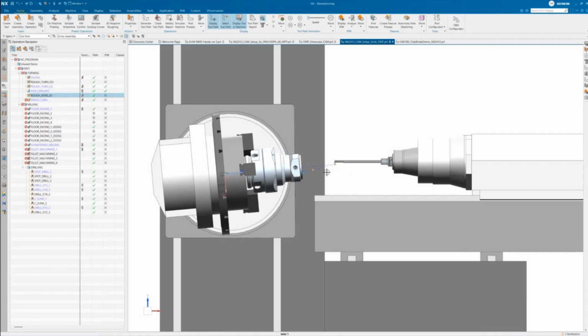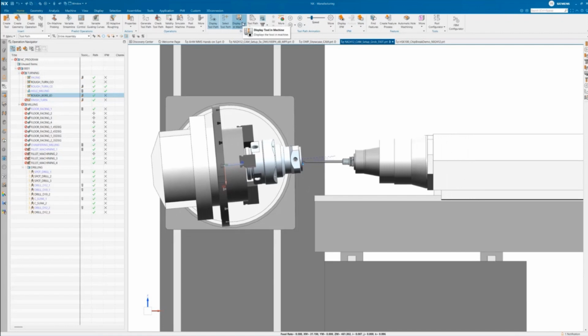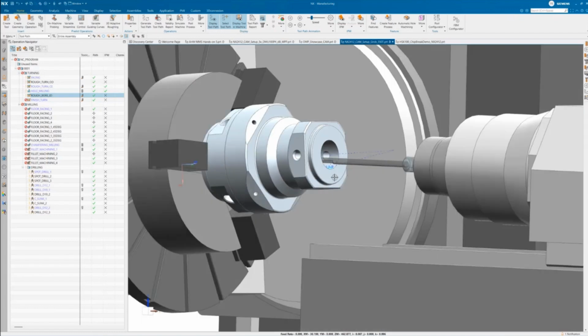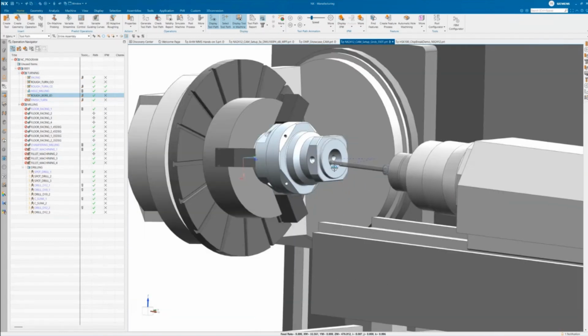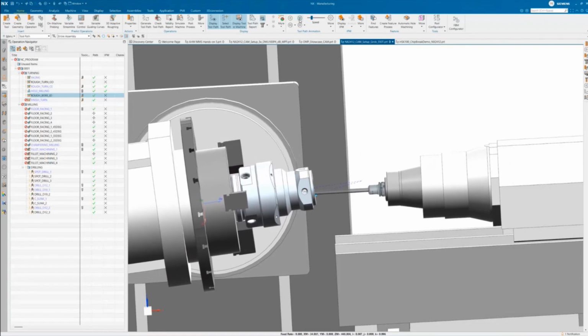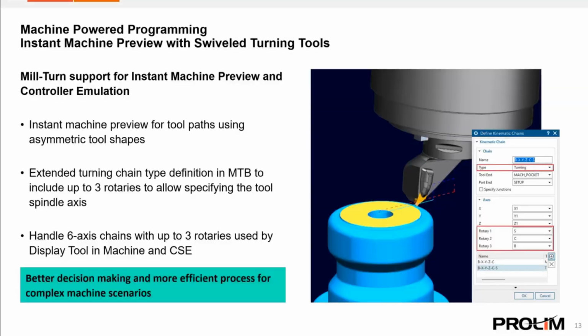That's approximately the 5 degrees we have mentioned, and now you can run the toolpath animation with the display machine tool, so that you can see if there is any collision, and now you'll be able to change the tool angle, and so on. So that's how it is helpful for us. So let's see what we got next in our slide deck.